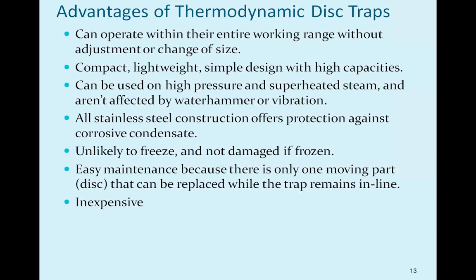Typically they're stainless steel, so any corrosion issues are eliminated. They're unlikely to freeze. They typically don't hold any condensate in them, so even if you shut down a process that these are on and it's outdoors, usually it will end up draining any water, or because it's stainless steel, you won't get cracking. Easy maintenance.